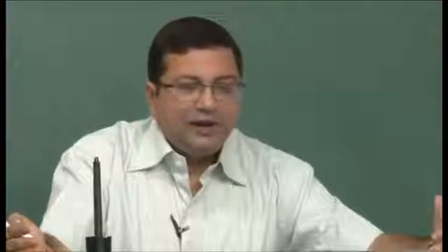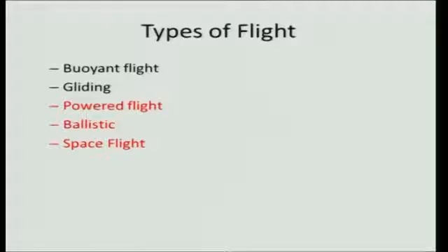So, powered flight is the third category, particularly in this context I am talking about powered flights as vehicular flight like aircraft or helicopter flying with an engine, that is what a powered flight is. Another category is ballistic flight, where you provide a very high initial velocity to a vehicle or an object, and because of its inherent inertia or momentum, it just propels through the atmosphere. So, that is ballistic flight.